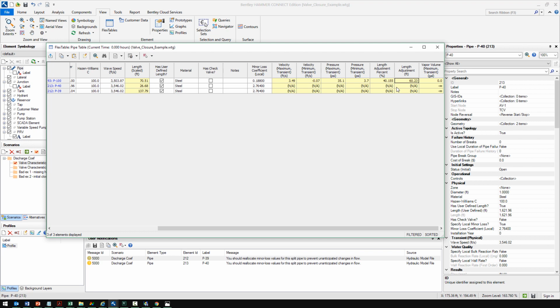If it is at a critical point, it could still be critical as far as how it reflects off of that closed valve, and you've got your air valve next to it, and it could be significant. If you have a case like that, then I would definitely do a sensitivity analysis. Try a much smaller time step so that it's not a large adjustment.